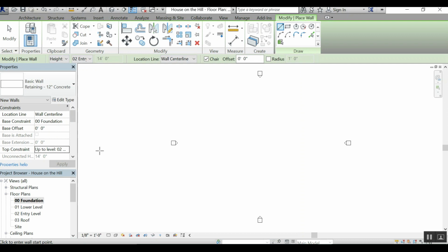Now what I want you to do is go to the lower right area in the middle of all four of these cameras. So right about here, say. I want you to click and move the cursor to your left. And you can see as we're drawing it, distance shows up. As you're moving your cursor to your left, just type in 40 tick mark, 40 feet. You don't need to type this into any kind of special box. Just as you type, a box will appear where your distance will show up. Just type in 40 feet or 40 tick mark and hit enter.